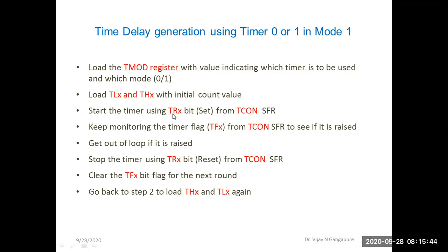And when you set this TR bit, which means you start the timer, these pulses will start reaching the timer register, and the count in this timer register will start incrementing by 1 due to each pulse it is getting.